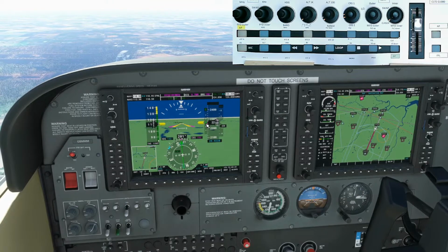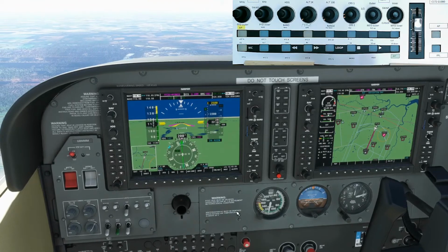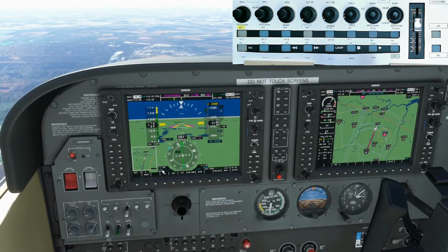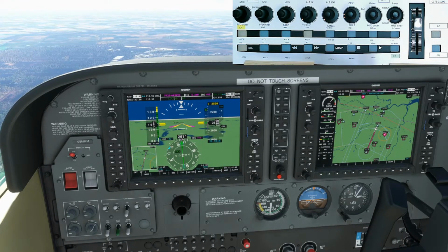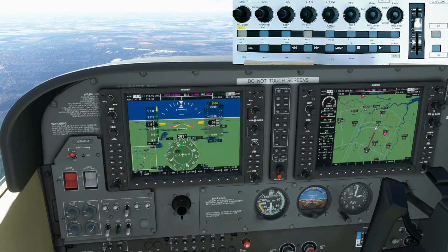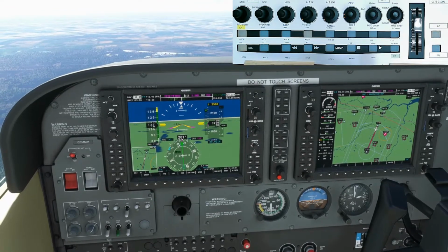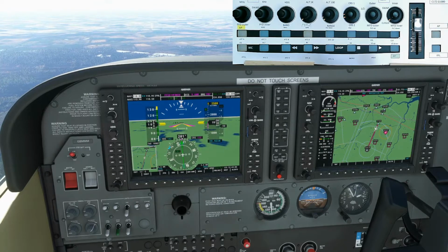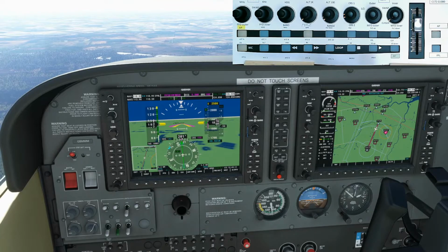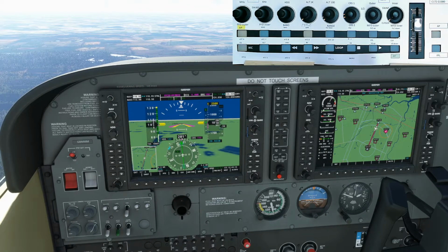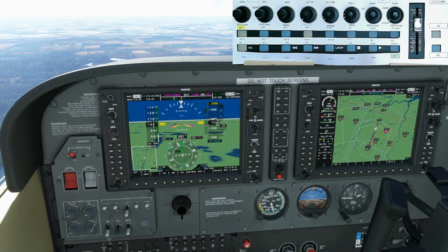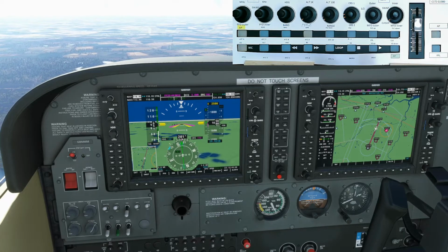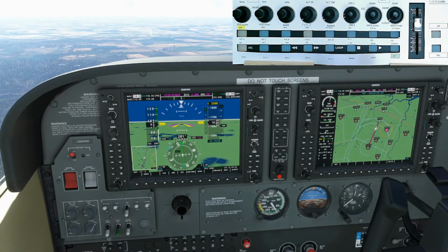We've picked up and we're now descending on the glide slope, airspeed increasing, so we'll pull back on the throttle as I head towards the flaps down speed. And we've got 7 miles to run now. You can't see what I'm doing, but I'm slowly bringing the throttle back. Slowly bringing that speed down.